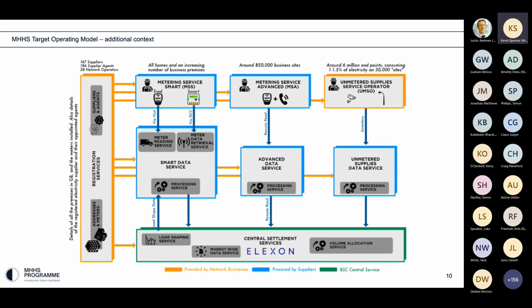Yeah, so the load shape is for a category of metering systems, the average of the actual data for that subset of metering systems. So it's actually kilowatt hours by settlement period, isn't it? It is, yeah. So that would give you an average of the energy in each half hour for that particular load shape category.